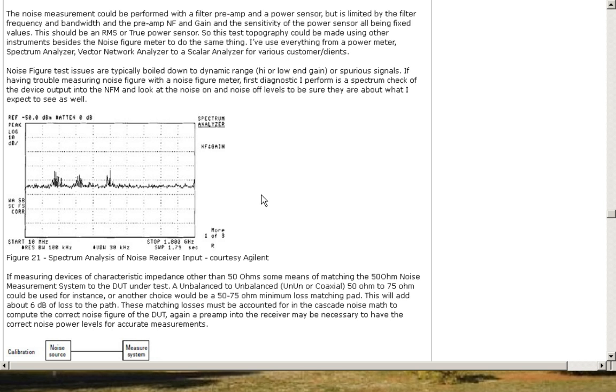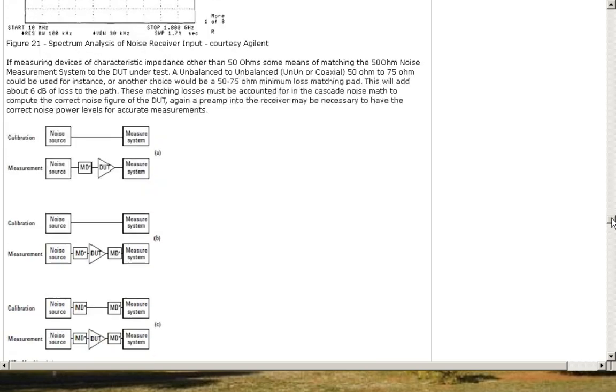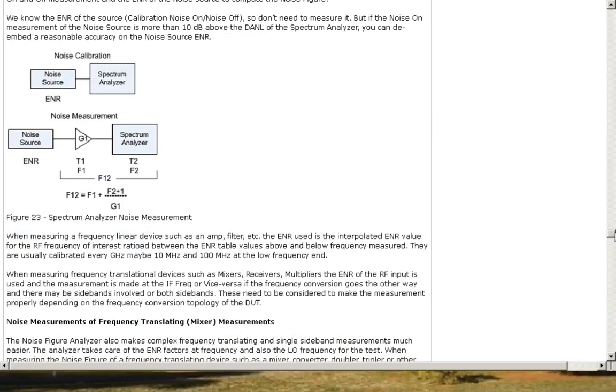Then you increase the signal level into the receiver input, and as soon as the audio signal goes up by 3 dB, now you know what the sensitivity of that receiver is, based on microvolts. That's your signal to noise ratio of the whole input.